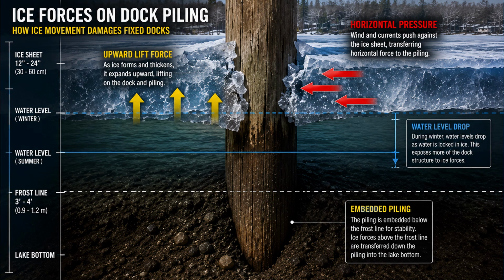Pilings resist enormous loads, but ice changes everything. If ice bonds tightly to the piling and the water level changes, the ice can attempt to lift the piling. Meanwhile, expanding ice pushes sideways. Those combined forces create bending moments. Eventually, steel bends, wood cracks, concrete fractures, connections loosen.